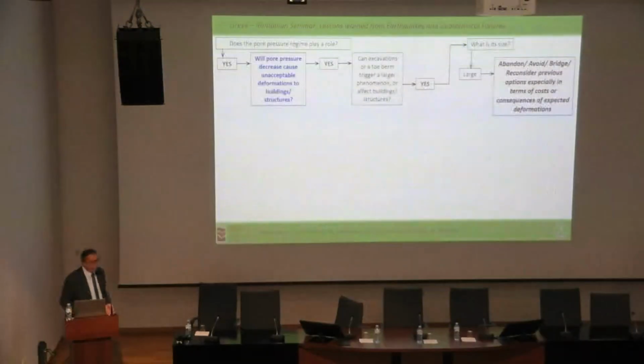Does it play a role, the pore pressure regime? Yes, it does. Fine. Will the pore pressure decrease cause unacceptable deformations? Yes. Can excavations or top berms trigger a larger phenomenon? Yes. What is the size? Large. Abandon.